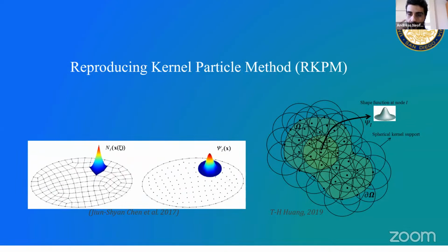Going back to the second point of the 3 points that we discussed in the second slide, the way we address the design dependency, as a start, was to bring a particle approach into our level set method. Specifically, we're using the reproducing kernel particle method. The idea is that now, instead of having elements with predefined connectivity, we build our shape functions relying entirely on a set of scattered points or particles that do not have any predefined connectivity. So we are free to lay the particles over the domain any way we want. We can lay those on the boundary and exactly track the boundary to address the design dependency. As you see here on the right, we lay the particles over the domain and we have these shape functions that now overlap over the domain.